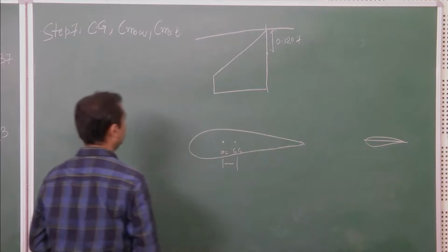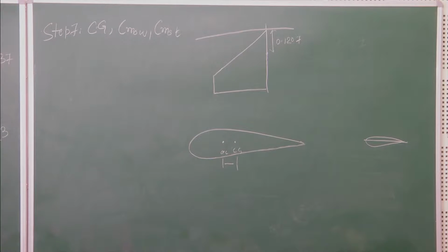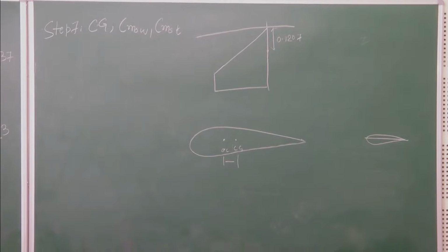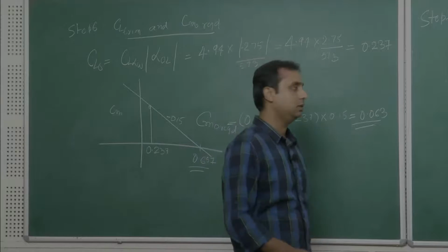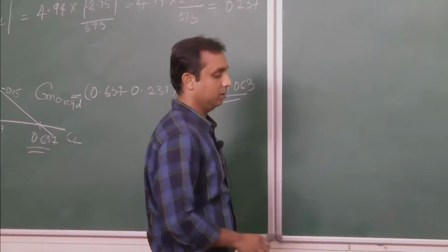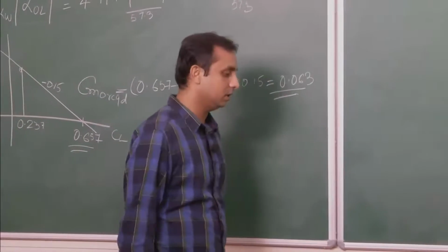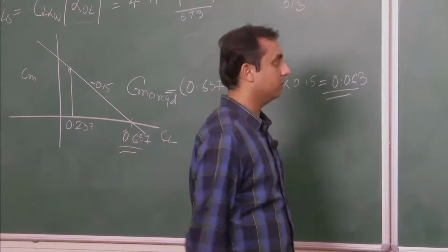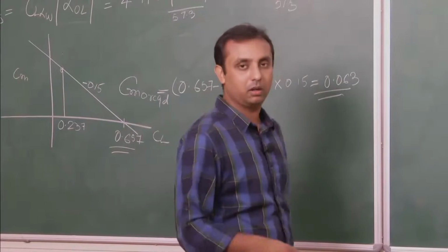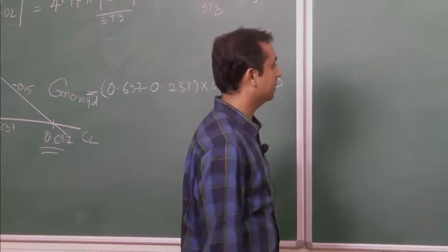So for a fixed wing UAV, we use a lithium polymer battery, so your mass does not vary during flight. So we can assume CG is fixed in the case of UAVs. But in the case of a jet, during flight, with the consumption of fuel, your CG might change, so you have to consider a range of CG for this calculation. But in our UAV, we don't have to worry about that since CG does not vary.